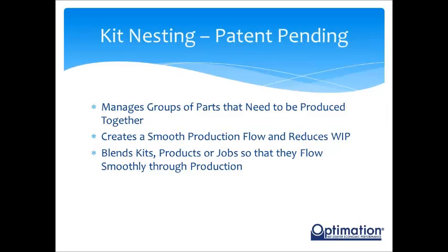We want to be able to avoid the material efficiency problems by blending kits together. So as we complete kit 1, we want to blend into kit 2 and not have major gaps in material efficiency and get that tail-off problem that would happen if you were just trying to nest these kits by themselves without regard to what comes next.